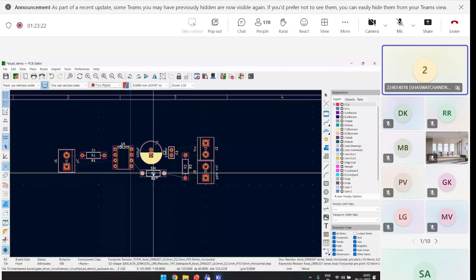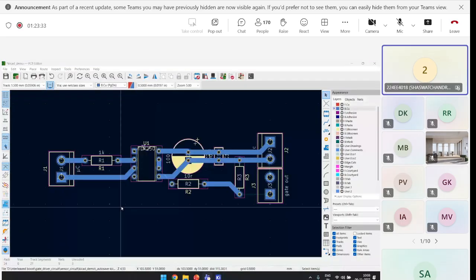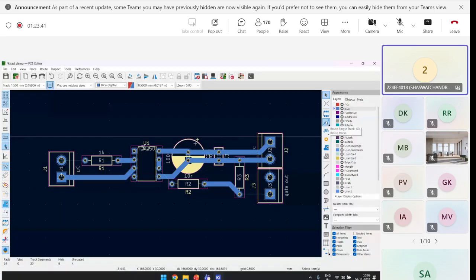Yes, sir. How is this schematic drawn with this wire? Okay, yeah. Again, I'm telling. Let me delete this. So here there is an icon, right? Route signal track. You can click on this, and when you go to any terminal that you want to connect, after you click on this, KiCad will show you where this terminal will go.